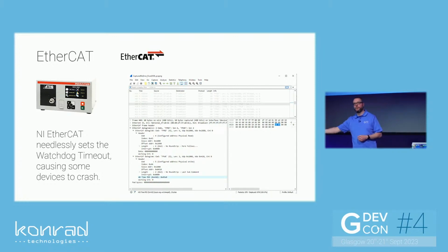What did TwinCAT do differently to the NI drivers? And that's where you find just one class is written by the NI master drivers that the TwinCAT drivers don't set. Who knows why? Nobody does, apparently. There isn't anyone at NI anymore who knows anything about EtherCAT.